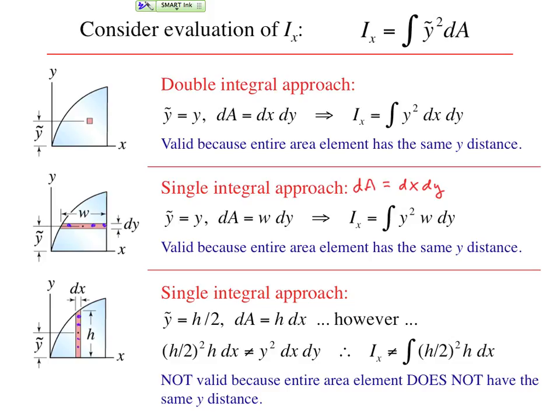When we were using this construction for a centroid calculation, it was okay, because the position appeared in the integrand as a linear function. We could compensate for every material point having a different vertical position because a material point just below the midpoint of the differential element, this one for instance, was exactly offset by a material point just above the midpoint by the same distance.